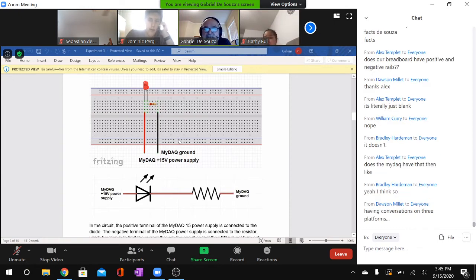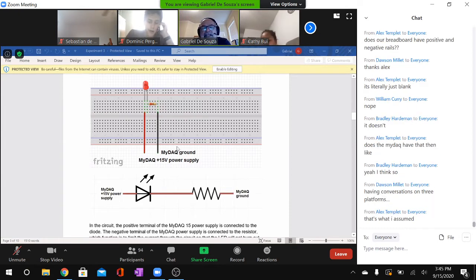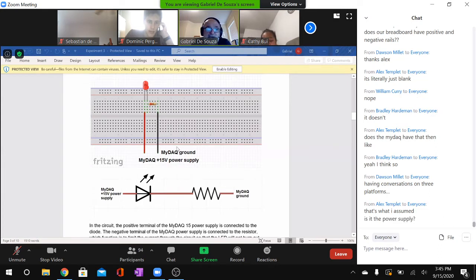Same thing down here. And many times you forget to do that, and usually your circuit's not going to work properly, but it's very easy to find out if it is working properly or not. You basically get your multimeter and you test the ground and the VCC connections, or the positive voltage connection, of every one of your devices until you find one that doesn't have it.